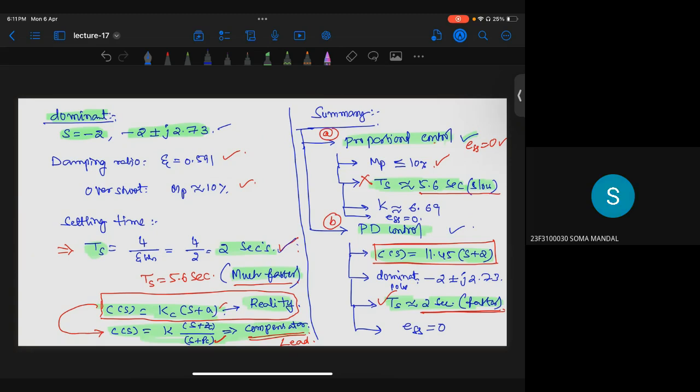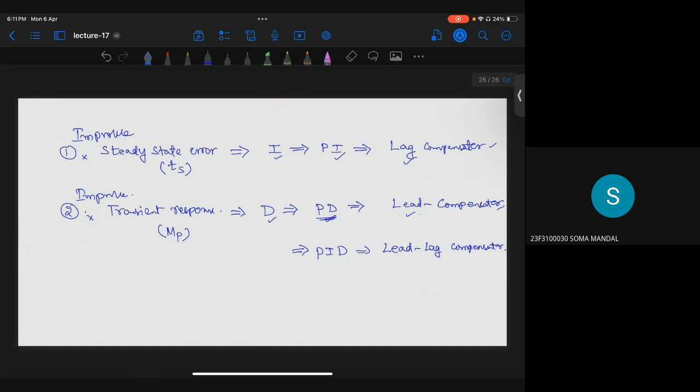Yes. For MATLAB, what we have to do? See, what is the purpose of MATLAB with respect to the root locus? If we just give rlocus of your numerator coefficient and denominator coefficient of your open loop transfer function, it will directly give you the root locus plot. Is this clear? Sir, do we have to install and download MATLAB? No, not needed. You can use the online MATLAB also. Online free version is already available.